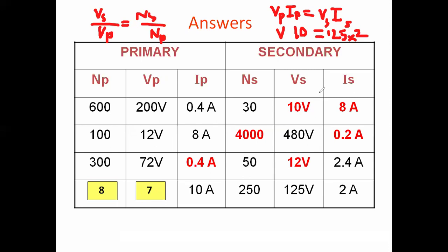So what answer we will obtain? We can get it by solving it. The answer will be 25 volts. Okay, because turns are not known, so we will find out the turns now using voltage turn ratio. So that is 50.